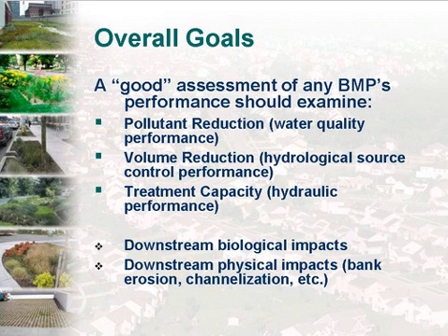Yes, good point, Nico. At some point, we typically design water quality BMPs for smaller, frequently occurring storms based on a water quality capture volume that's generally, around the United States, less than a one-year return frequency event, perhaps an 80th to 90th percentile annual event. Well, every now and then it rains harder than that, and some of the flow will bypass the BMP because the BMP just can't keep up with the flow. So that's the third bullet.